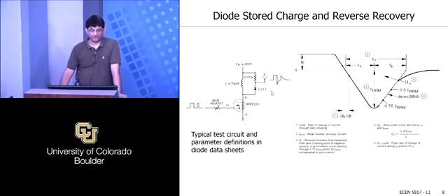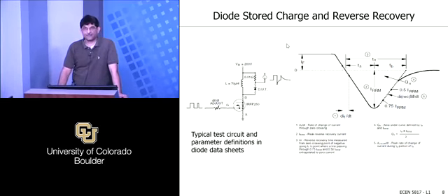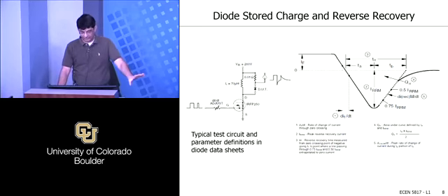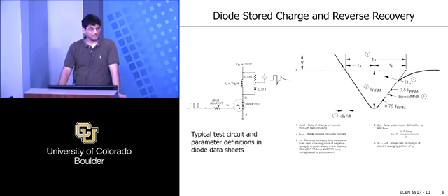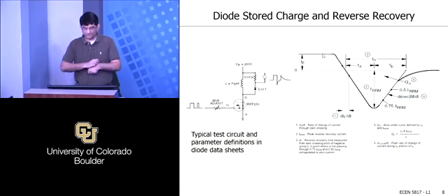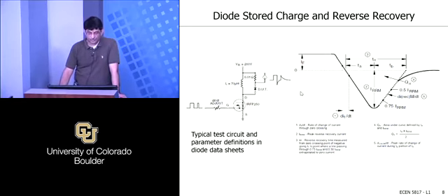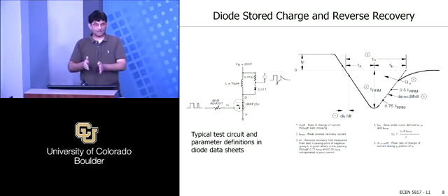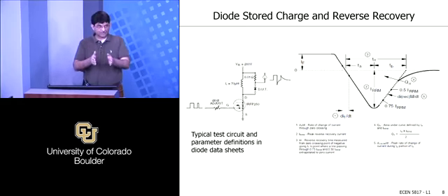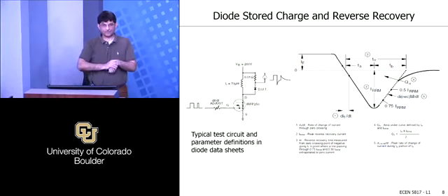I want to say a few words next about the diode, because you're going to have a homework problem where you'll be solving a similar kind of problem, but not with a snappy diode, rather a soft recovery diode. A snappy diode is where, as soon as you remove the charge, you've reached the point where the junction can start blocking, essentially all the charge is gone, and suddenly the voltage will rise across the diode.